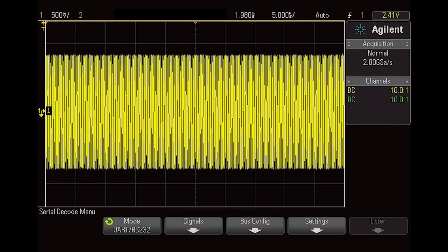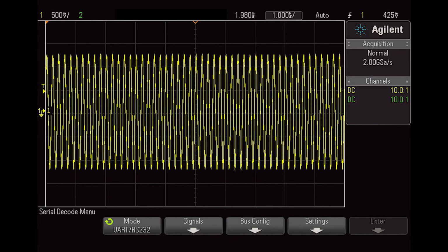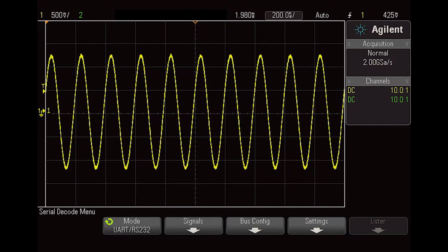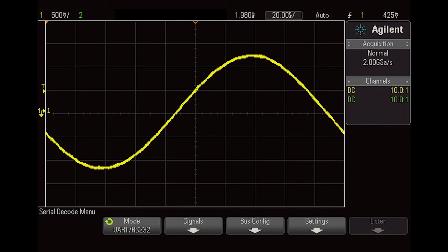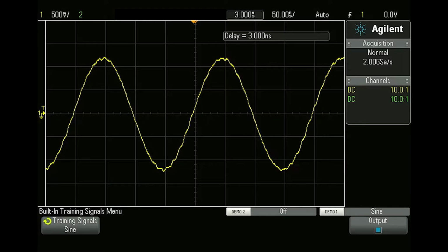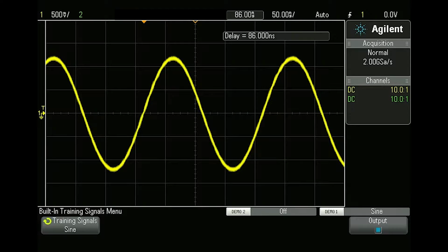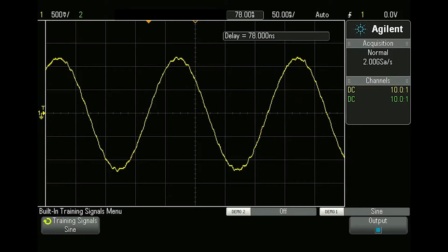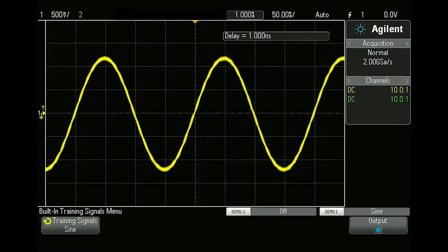The horizontal adjustment dial changes the time range per horizontal division for the display. Again, this is used to zoom in on the signal until it can be clearly seen. The horizontal position dial adds a delay into the signal so that it moves left and right along the horizontal scale. This can be used when comparing 2 signals so that they can be aligned.